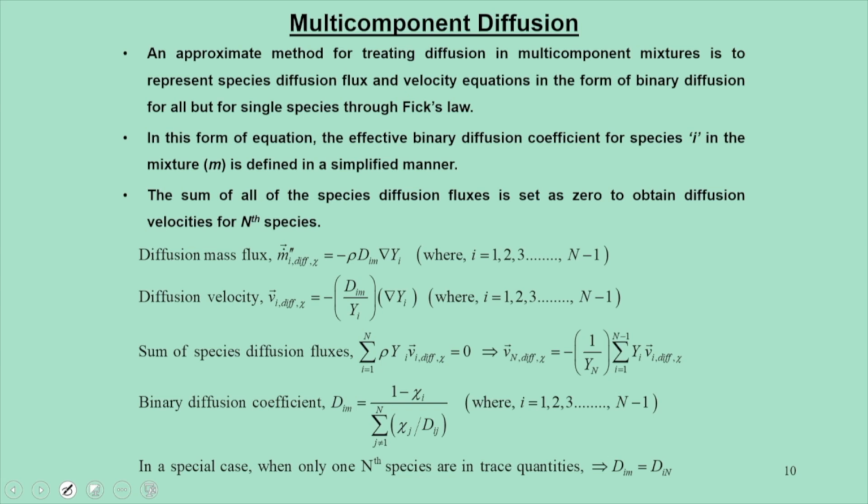And the most important thing that I need to emphasize here is that the diffusion velocity due to concentration is given by this. So this has to be taken into account. Now for binary, you have terms like binary diffusion coefficients for species, and species fluxes or diffusion fluxes.